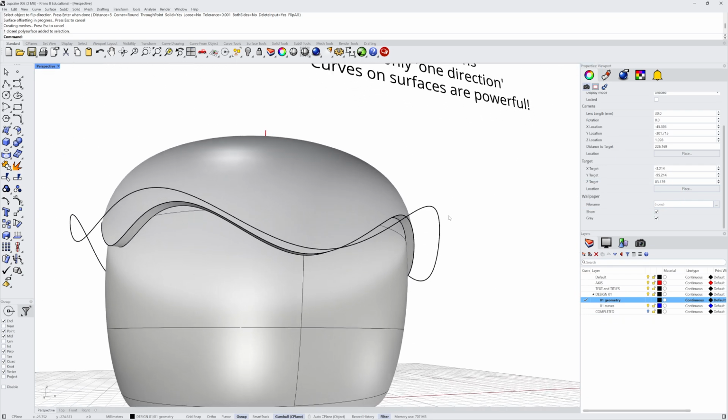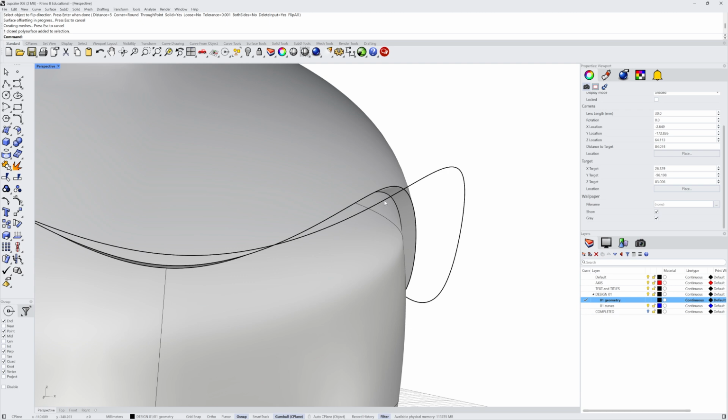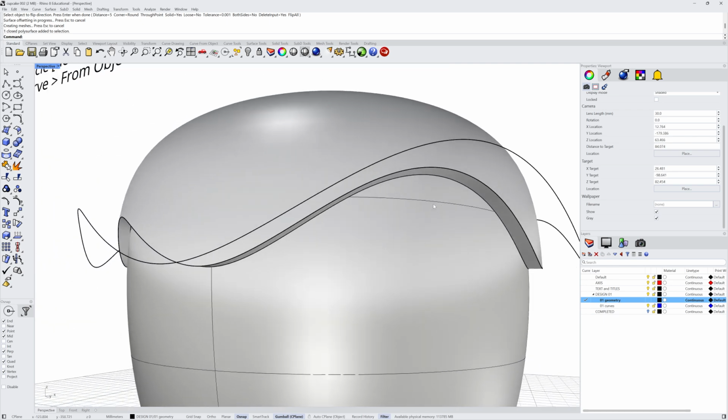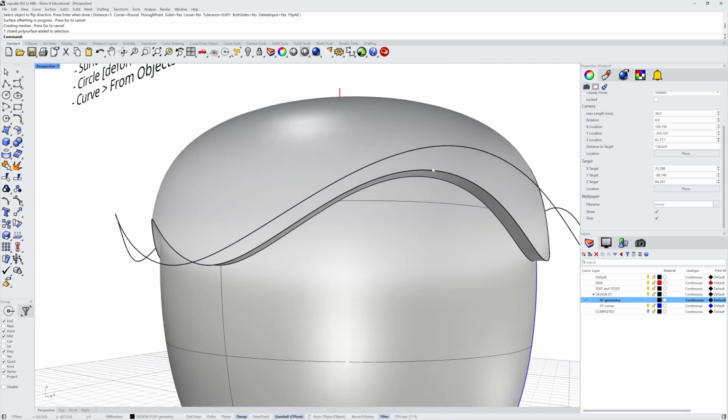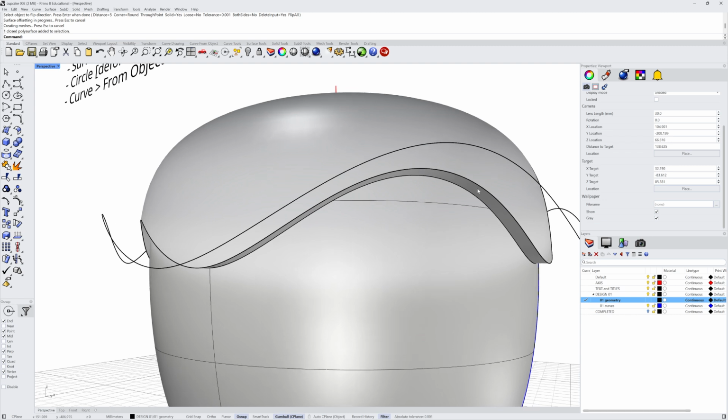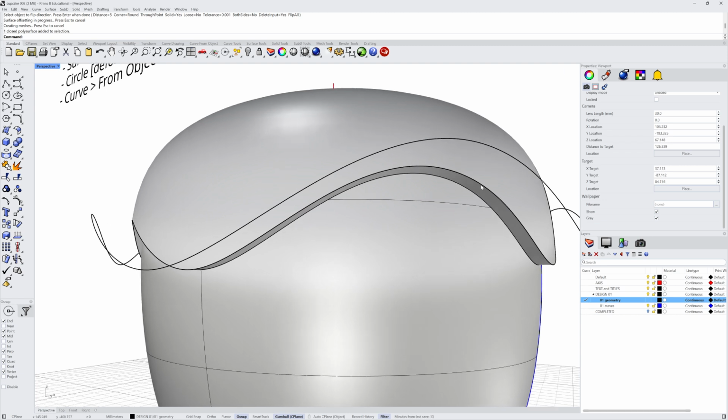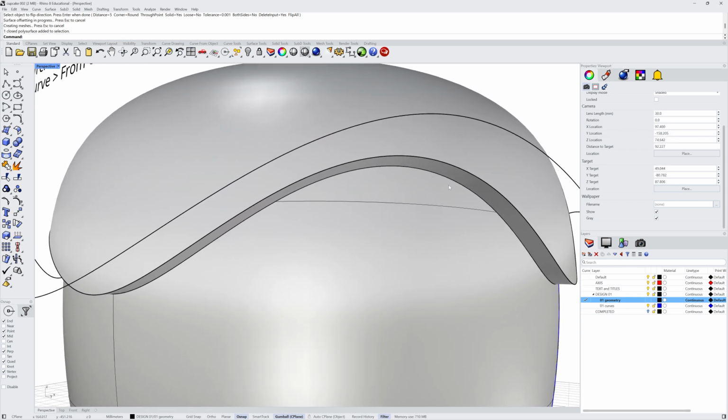Now the final step here is to give this a little bit of a fillet, so a little radius around the corner. And the reason I always type in specific numbers is so I can remember them later. And we had given it a thickness of 5. That means we can't be bigger than 5 if we're going to round this corner off. I will select the number somewhere in the 3 to 4 range. So let's do that right now.